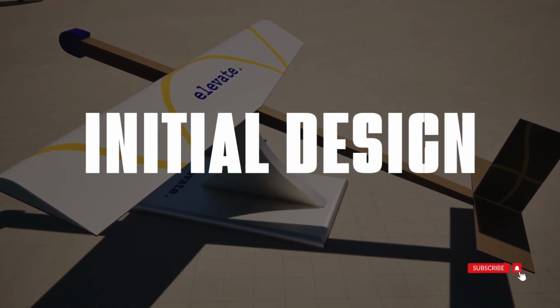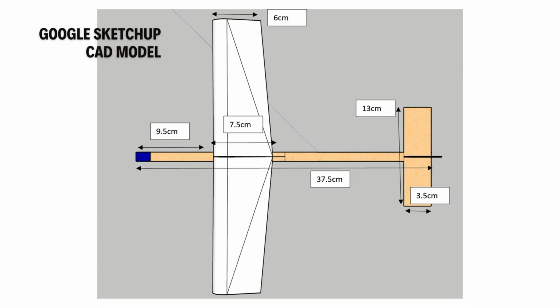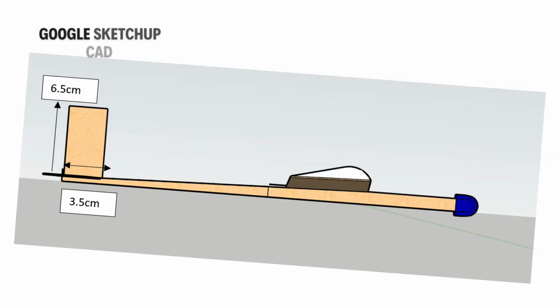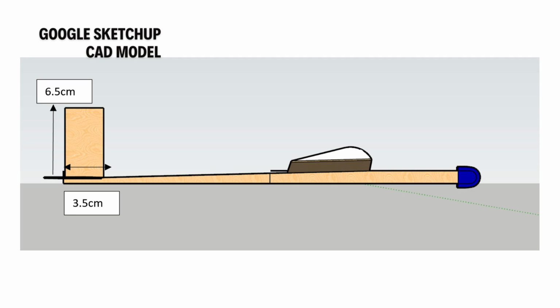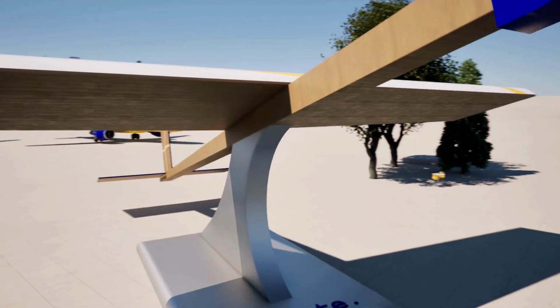By incorporating all the research I gained, I created my first model proposal using Google SketchUp. To make sure the glider kept intact as per the requirements, I chose to base every design choice off of improving stability. For example, the wings would have a dihedral angle of 3 degrees to improve lateral stability, while being slightly tapered to reduce drag. The wings had an aspect ratio of 4.7, which was optimal according to the research.